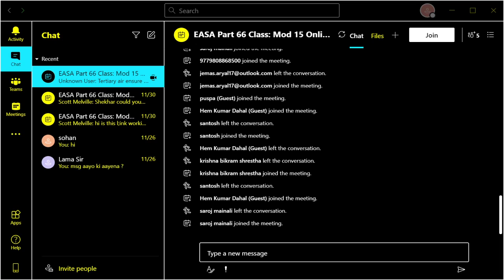Ball bearings are divided into 4 main groups. A ball bearing, as it sounds, is just a ball of steel in a cage. Radial bearings, angular contact bearings, thrust bearings, and finally instrument position bearings. We don't speak about these much, but just be aware of instrument position. These are smaller, finer ones for gauges and that sort of thing. The 3 main ones we'll look at are the radial, angular, and the thrust ones.